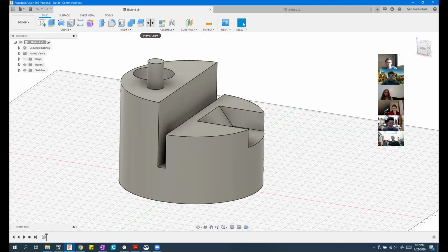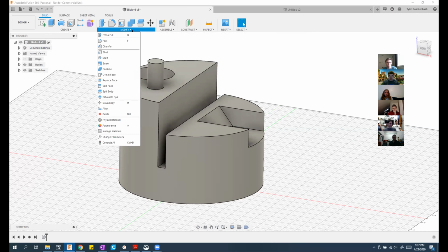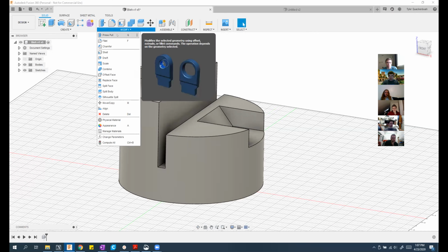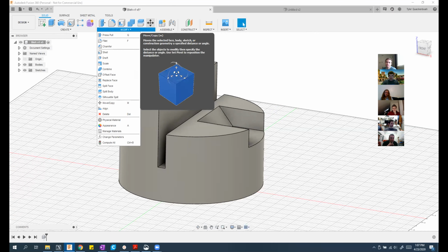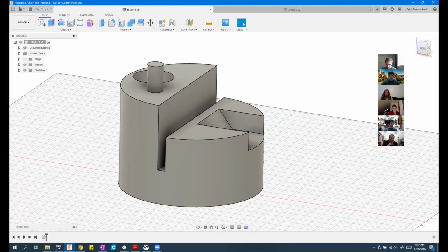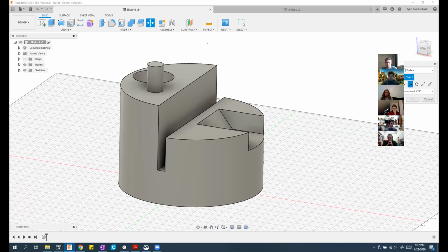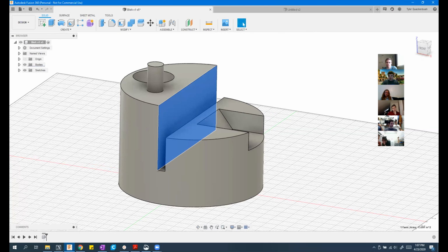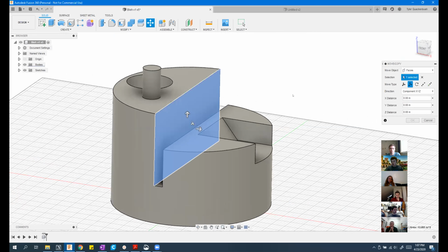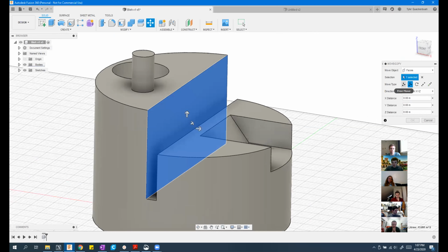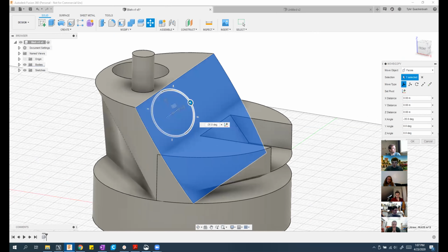And one of the cool things that I learned that Fusion people do all the time is they use this press pull function, and they use the move tool a lot. So when you select faces and use the move tool, it opens up right here. You get your move copy box, and there's this free move button, which does a lot of weird things.